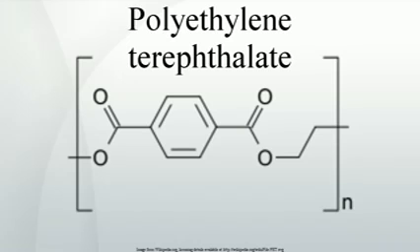At room temperature the molecules are frozen in place, but if enough heat energy is put back into them by heating above Tg, they begin to move again, allowing crystals to nucleate and grow. This procedure is known as solid-state crystallization. When allowed to cool slowly, the molten polymer forms a more crystalline material. This material has spherulites containing many small crystallites when crystallized from an amorphous solid. These bottles, if placed in direct sunlight, can withstand it for a very long time, approximately 5 years. As time passes, these bottles become opaque.